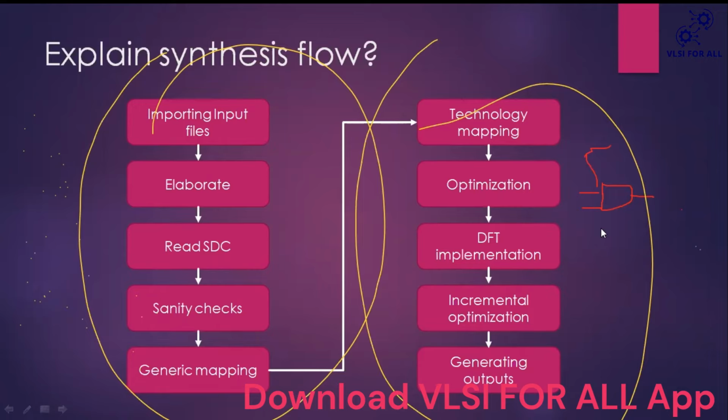After doing this incremental optimization, we have to generate output files. What are the output files for synthesis? One is the gate level netlist. Another one is SDC. We gave one SDC as an input, and that SDC has to be generated again. So the gate level netlist, SDC, the timing reports, and scan depth are the major outputs of the synthesis flow. I hope everyone understood this.